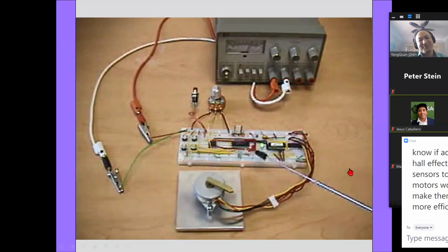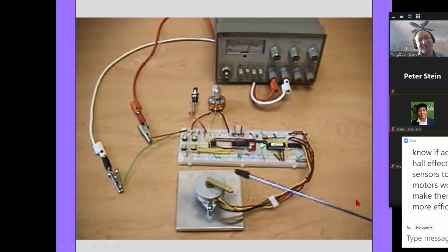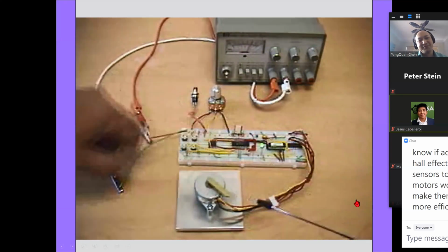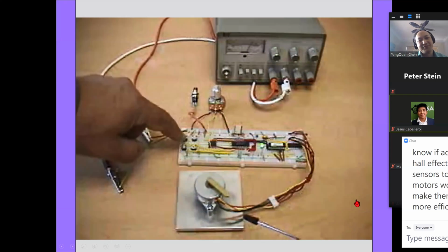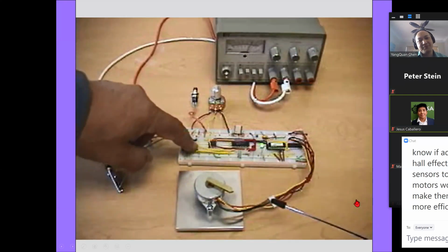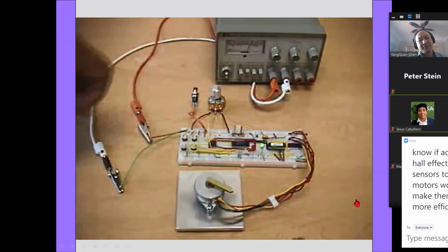The speed LED is off, but the speed we're running at, which is very fast, is used to move to the index positions. It's important to note that that was a very fast speed, and if you try to move to the positions starting at 0 speed and immediately go to that fast speed, it cannot track properly, and the motor does not move the full 45 degrees, or in this case the full 180. So you just buzz in that one place because the motor is stepping too fast for the rotor to respond.